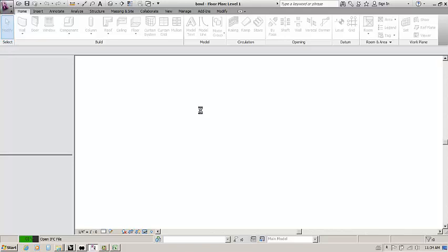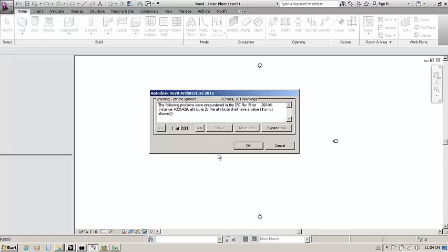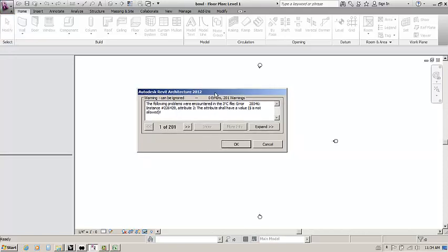And the IFC functionality I've only just been implementing, so I'm just starting to test it and work out, I guess, how that would best function. It seems that every object you define in the IFC file can have a certain set of properties and parameters attached to it. At the moment, again, this is coming from the perspective of trying to generate data for manufacturing the concrete elements. So we get some warnings here, which is a syntax issue where I'm using this $ sign for a particular attribute. I need to fix that.